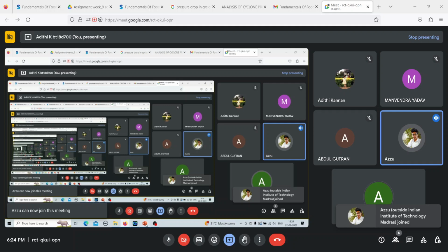No, centrifugation is not used for all of the above processes. During the centrifugation process, what is preferred is that at least you have one component that is liquid. You can either have a solid-liquid mixture that you want to separate, or you can have a liquid-liquid mixture with different densities that you want to separate. It's very difficult to separate a solid from a solid. So separating soil from seeds and stone from rice are very difficult in the centrifugation process.